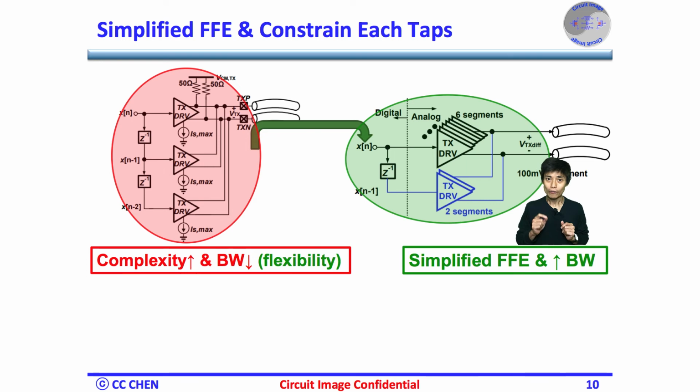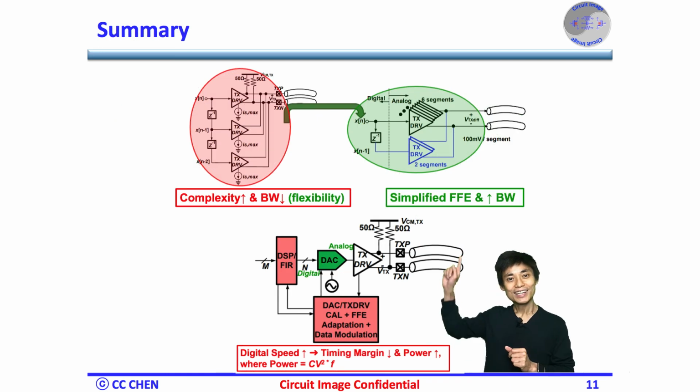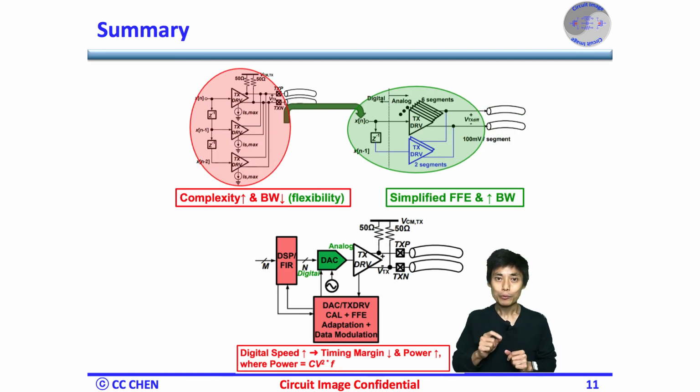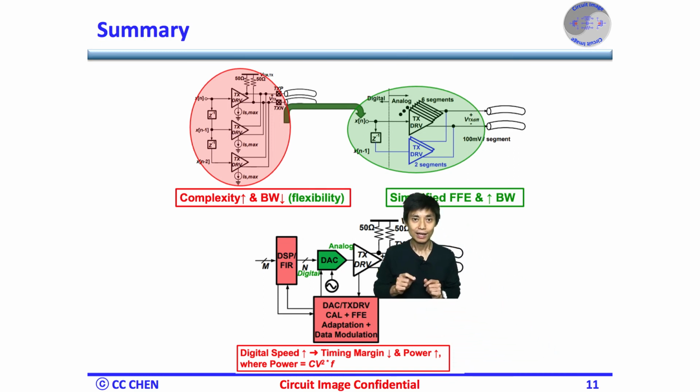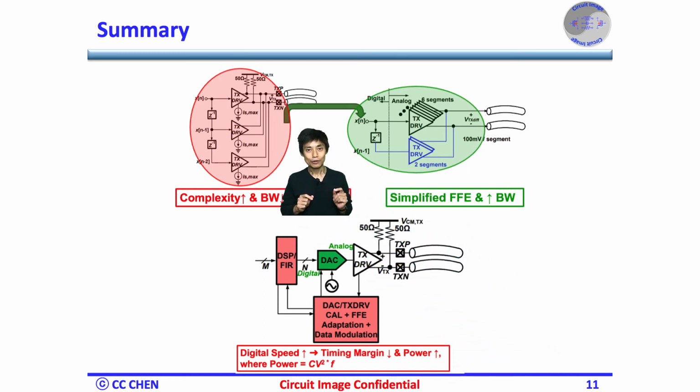Since the advantage of the analog-based TX driver is simplicity, most people will give up the FFE flexibility and keep enough output bandwidth. Here is the summary of why we need an analog-based TX driver in the SerDes system. Even though the self-loading of the analog-based TX driver with FFE could be a showstopper, most people will keep simplicity by limiting the FFE configurations.